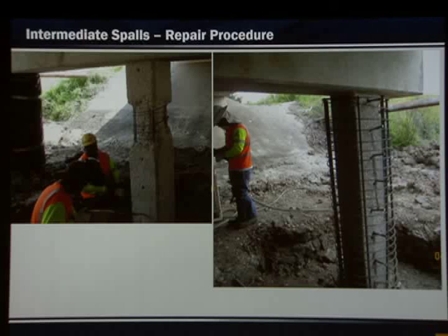So this is some pictures of the guys working on them. You can see them drilling and epoxying. I think we did it at 12-inch spacing. And we were lucky that there wasn't any damage to the pre-stressing strands. It was mostly the outer cage that had the damage, and it had a lot of rust. So then they put in the spiral cage and some additional bars.